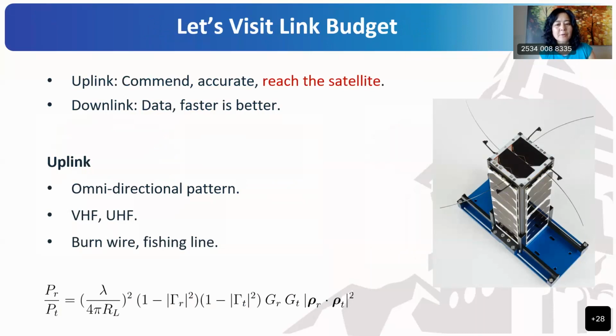Okay, so now we come to UHF band. I said putting the antenna around solar cells is limited to frequencies around S-band at least and higher. So how about UHF band? Now you ask, why do you want UHF band? This picture here is very similar to the CubeSat that was recently built by our university. The deployed antennas are UHF band. We said we don't want deployment, so we need to replace it. Basically, we need to replace a UHF antenna.